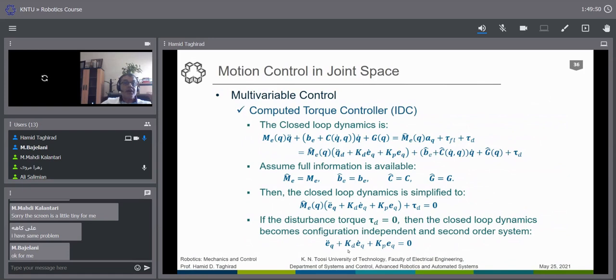You increase the gain to get to the saturation point, how much torque you can apply to the system. So you increase the gain as much as you can, not very high, as much as you can. The limit comes from the actuator saturation. And you keep the ratio between Kp and Kd to have the transient response working well with a very small overshoot. If you want a faster response, you can have a smaller zeta, but you get some oscillation. Usually in robotics, we don't need that oscillation.